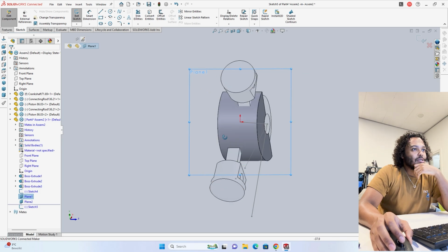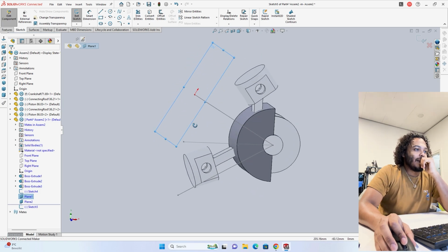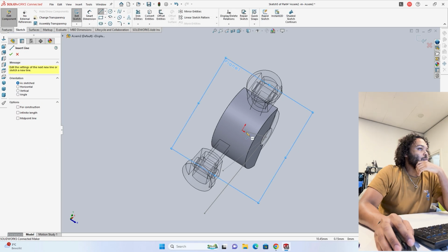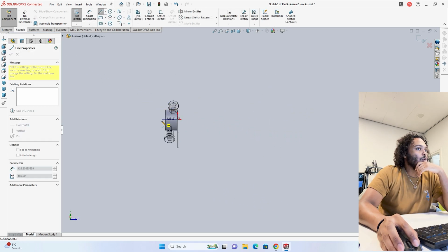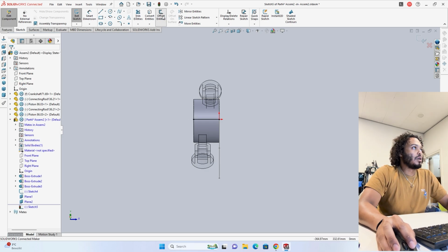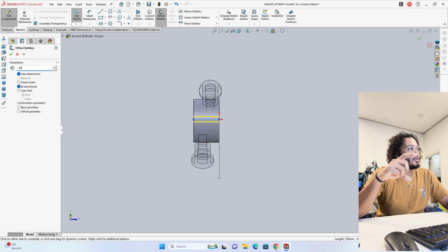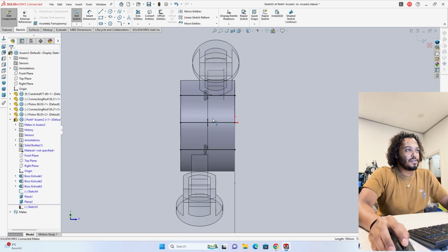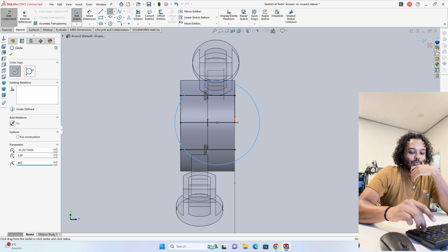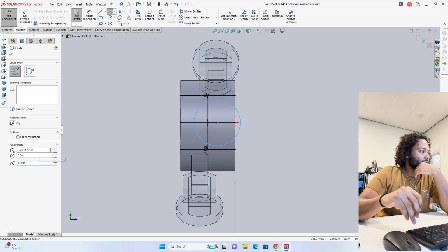So here, from this surface, we know it's actually perfectly on this line as well, because it's coming straight from the center of the circle of the crankshaft. We will have the bank itself, and the bank will need to be wide enough to support the 86 millimeter bore. So let's say 50 millimeters on each section. It will allow you to have an 86.03 millimeter bore, but I should divide it by 2 because that is the radius.